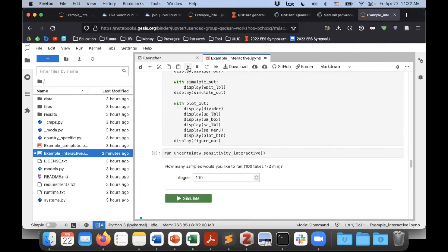Again, similarly, now you get to choose how many samples you want to run here. I won't advise a really big number, so you can get some results before launch. But if you are doing this for research, I also won't advise a really low number. If you are really considering doing analysis like this, the number of solutions you want to run depends on how many uncertain parameters you have in your model. For a system we construct, we use at least 100 or 1,000, at least 1,000. But for everyone to get to launch, I'll just type in 20 here.